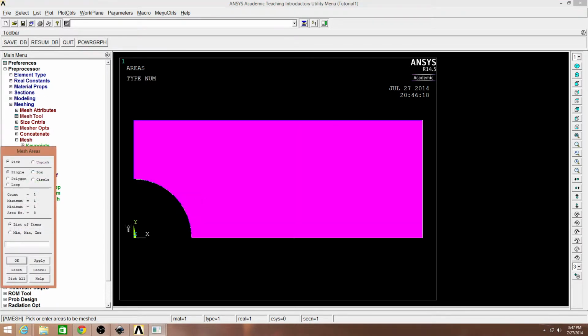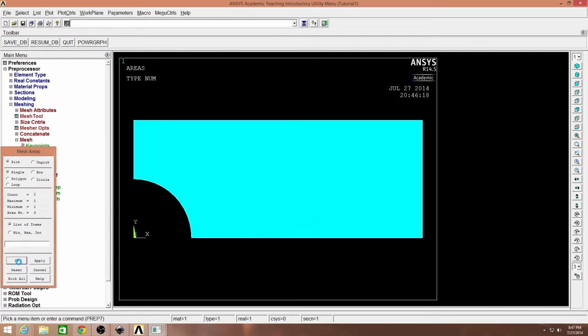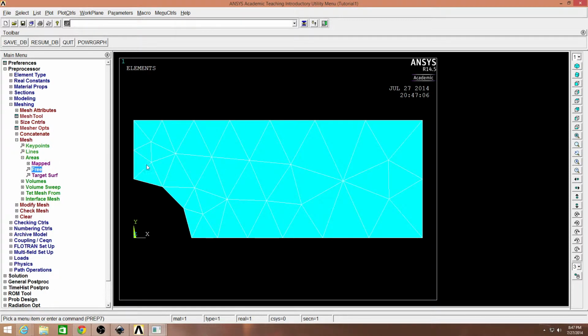And then just go ahead and click the quadrant and click OK. As you can see, a whole bunch of triangles have shown up, and these are the different elements. So loads, in theory, can only be placed on lines, but with the way that the analysis works, all of these nodes are connection points for each one of the elements. You don't need to know the complete details of this at the moment.